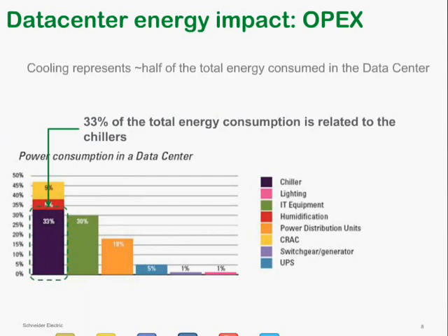In this case, it's a good example to consider that the outside heat rejection, the chiller plants, the air-cooled condensers and so forth, are actually a huge, huge energy hog for the data center. So it's important as we start to talk about economizers to reflect on the fact that when you look at cooling efficiency, we're not just talking about the indoor cooling units, the CRACs, the CRAHs, the in-row units, but we're also talking about the outside heat rejection.